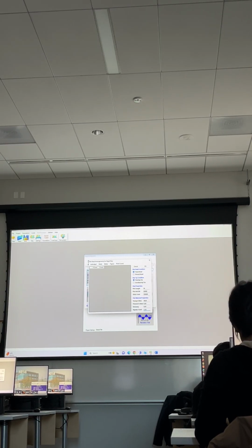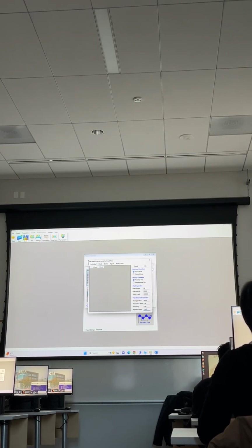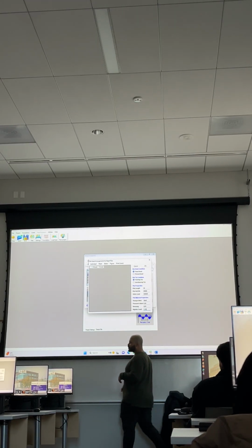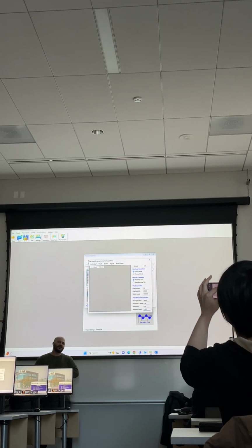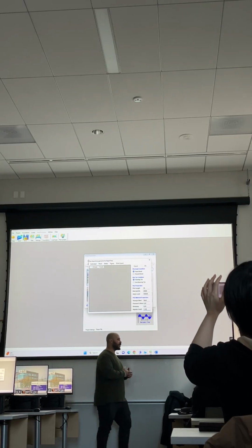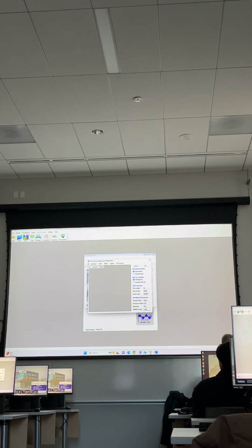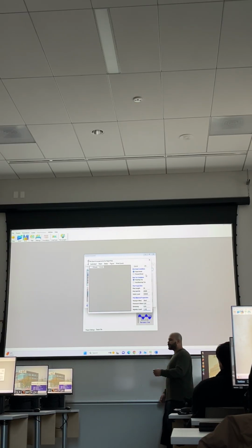For the square, it will be around 1.2, and for the rectangular pile, it will be 1.25. Usually we don't have a square or rectangular pile, so 1.12 is okay. Okay? So now you can define the pile coordinates, the x and the y, by yourself, manually.